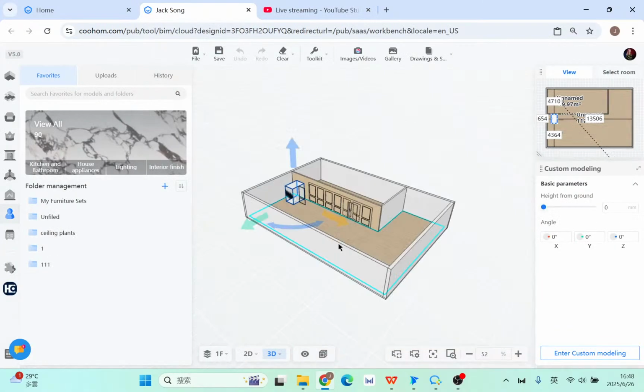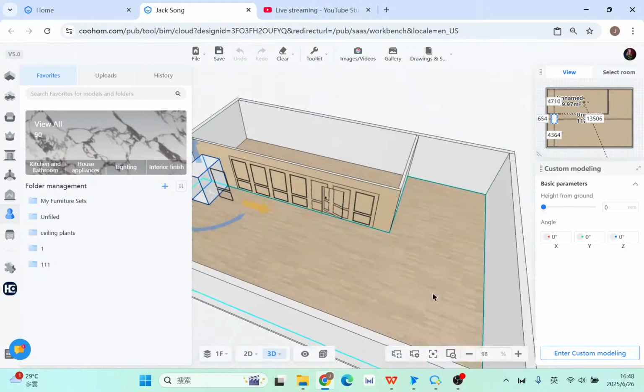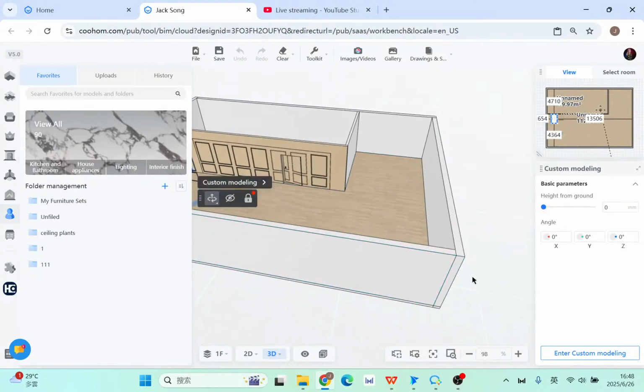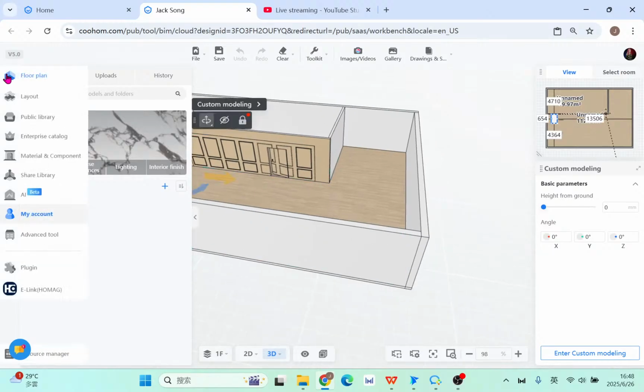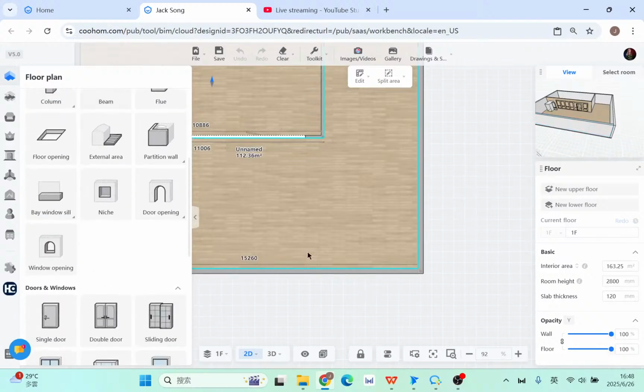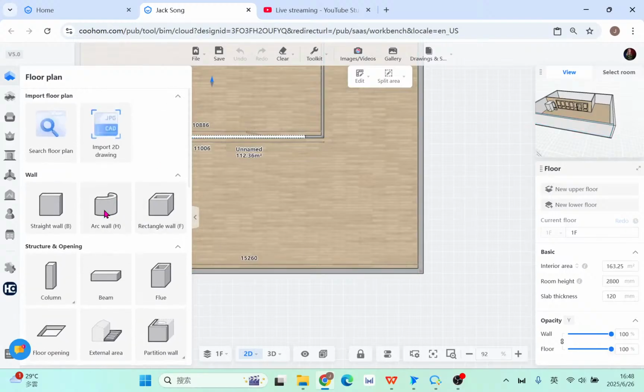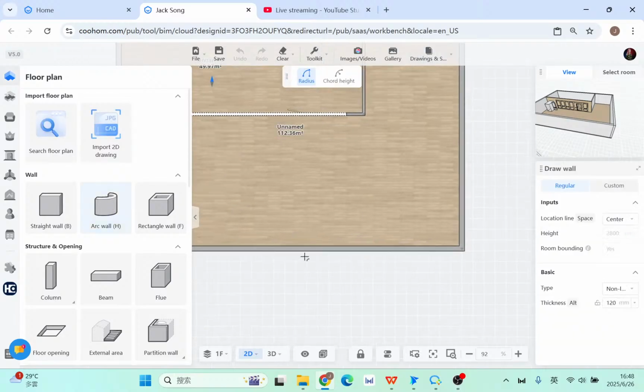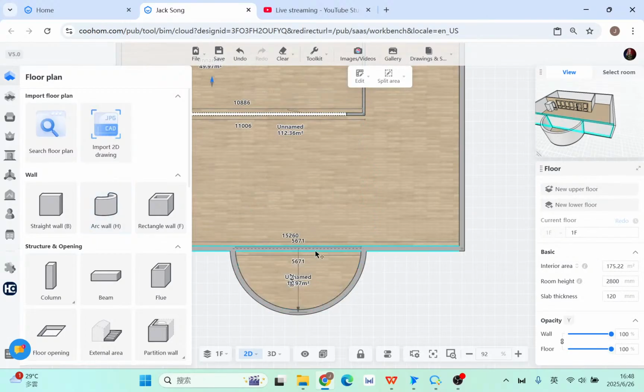And also, some of you before this class just raised a question asking if we can do some of the balconies, the round balconies. So actually, I can show you here, for example, you can directly first use the arc wall. Okay, either draw like this one. Let me turn back to 240. Click, click, and draw. Okay, just control it and then click to break.